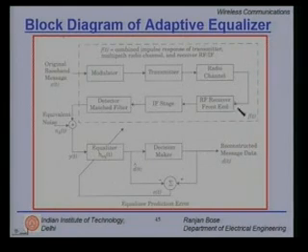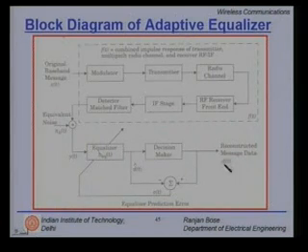It is received at the RF receiver front end, down converted to the IF stage, followed by the detector matched filter. Finally, there is an equivalent noise added and it goes through the equalizer. The job of the equalizer is to undo the effect of inter-symbol interference. Now, please note that this reconstructed message data d(t) we saw last time is an estimate and should match x(t).